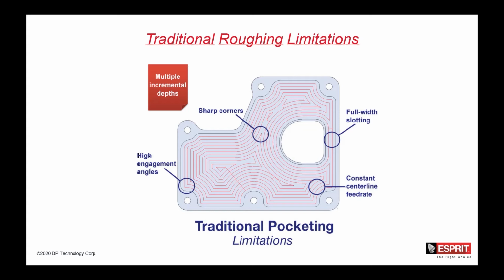So we then have to adopt reduced feed rates along the entire tool path. The cutting depth generally needs to be reduced to avoid tool damage, normally 1 times D, but this depends on the material being machined, plus using smaller depths of cut wears out the bottom of the cutting tool.